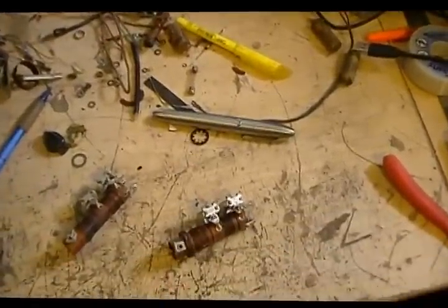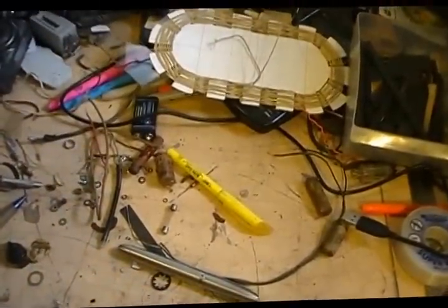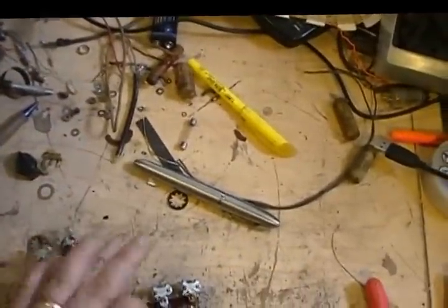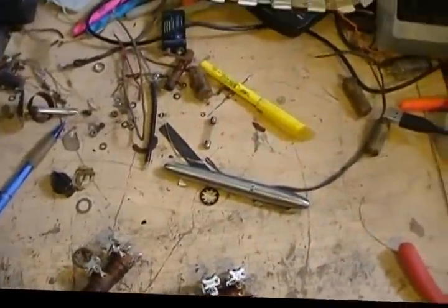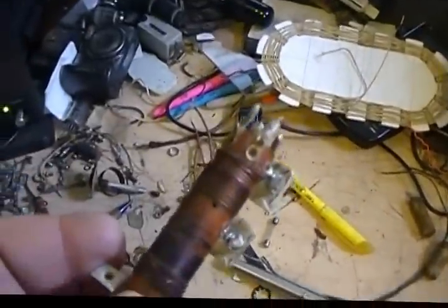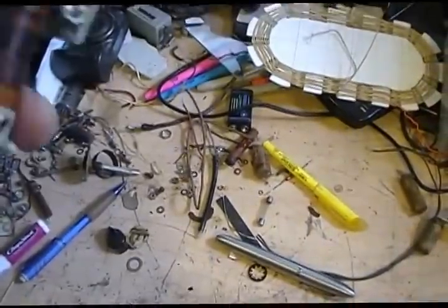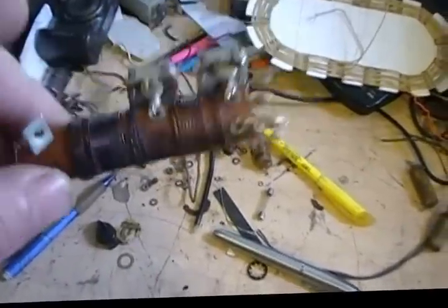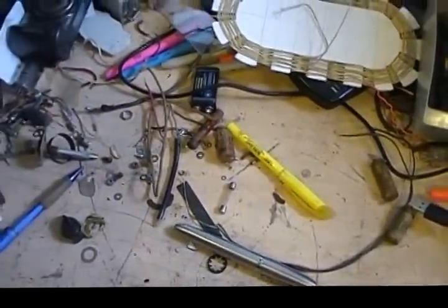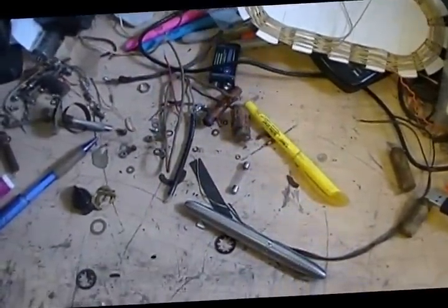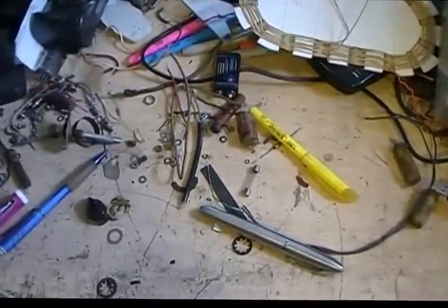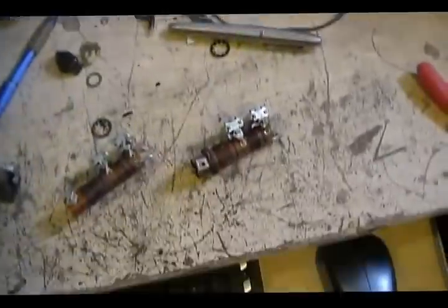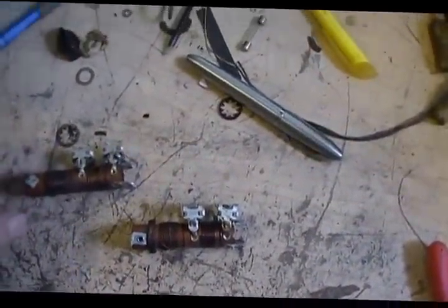the easiest way to deal with that is, first and foremost, I would deal with the oscillator coil first and then worry about the antenna coil after that. Secondly, if I got a multi-band radio, now if you got a single band, you don't have to do this because you only got one band. But when you got a multi-band radio, the thing I would do is I'd be concerned myself with the broadcast band only and do temporary tack-in connections.